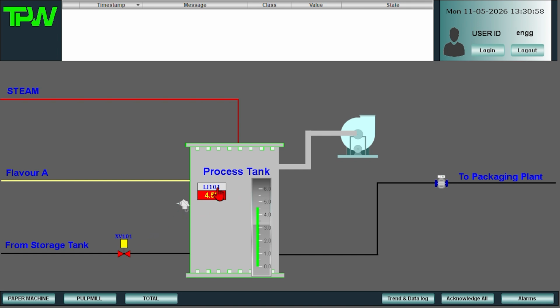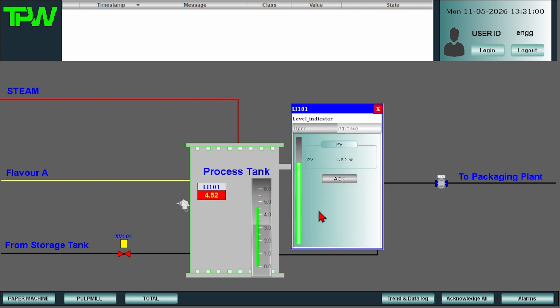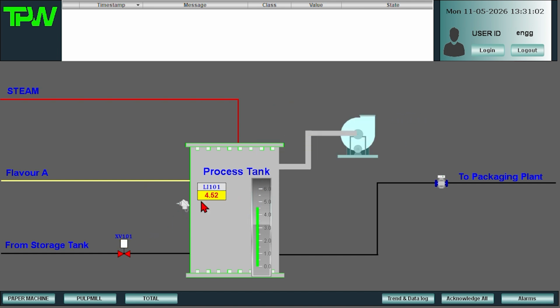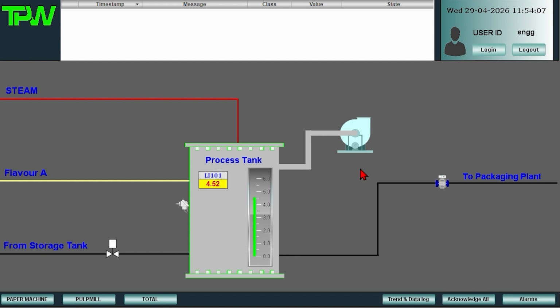In this module, we learned how to access the block from the SAKSHAM library, how to use the DACA block for analog scaling, implement automatic overflow protection, control valve using on-off valve block, visualize the entire system on SCADA. In the next module, we will implement temperature control and pasteurization process using the PID block and control valve.